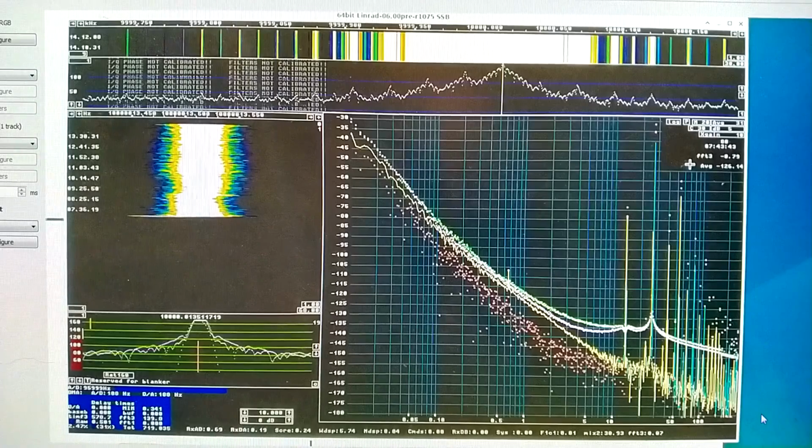Here is the phase noise measurement using the same sequence of data as in the previous Allan deviation. This is from nerds101, a video I made recently. This is much better than what I had previously, with one free-running oscillator and the other oscillator locked to it.